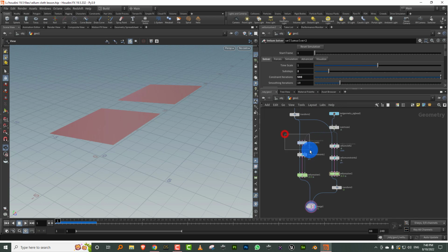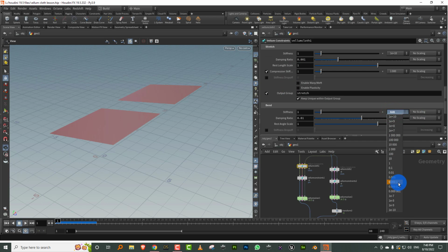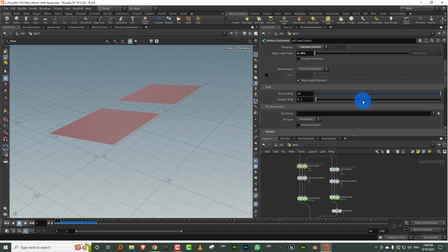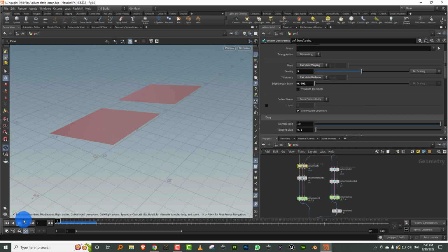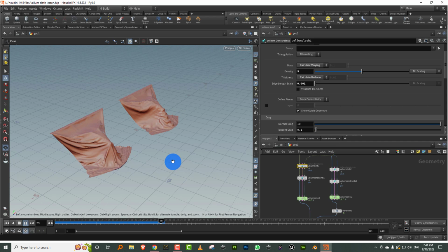And let's get this to something like that silk or satin thing that we were trying out. So let's make it 0.0001 and this is fine. Okay. So this should hopefully get very wrinkly and that should be more stiff. See, that's interesting, right? It starts to harden up the wrinkles because of the plasticity. So you get some pretty interesting results overall.